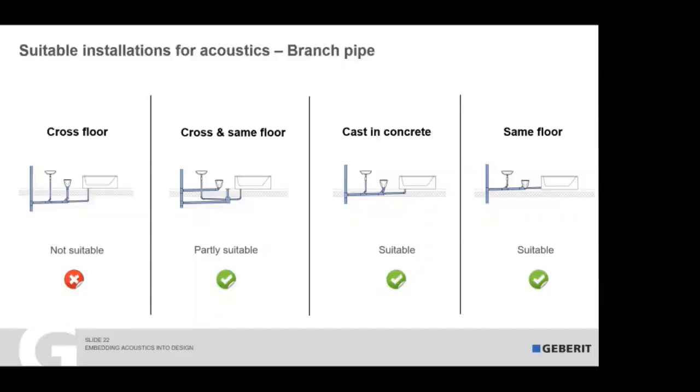Yeah, no, I don't think the HVAC system has any relevance, because HVAC systems are also mostly above 30 dBA. Mostly what we see in different countries is that the requirements are around 40 dBA. And then, of course, you can ask yourself, does it really make sense to consider 30 dBA for a piping system when the HVAC system is already at a higher noise level? Also there, you always have to consider the full building. As I said yesterday, the walls, the ceilings, the windows. What is the outside influence? Like we have seen even in the UK regulation, this is already 35 and 40 dBA. And then you can ask yourself, does it make sense to consider 30 dBA for the building? And if you have a good layout and you use a normal pipe, I think then you already have a good value for the installation.